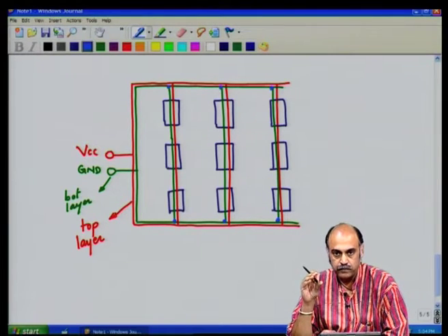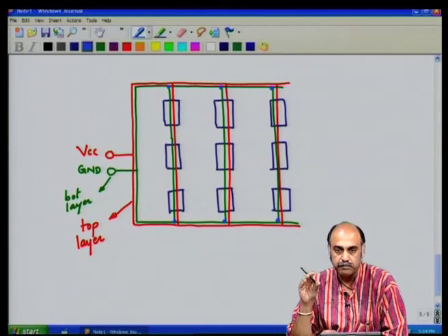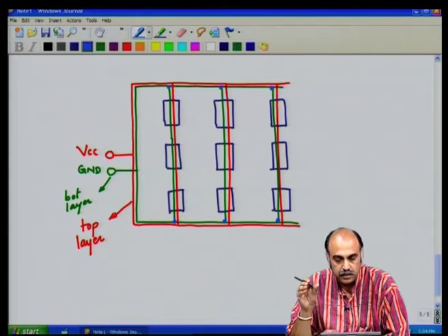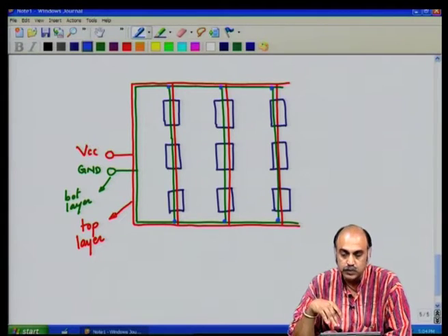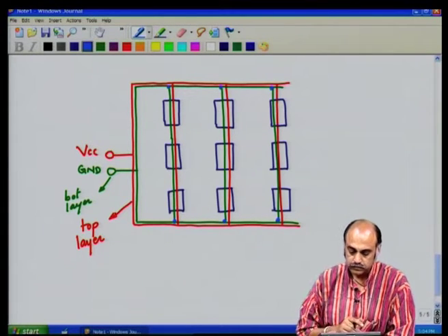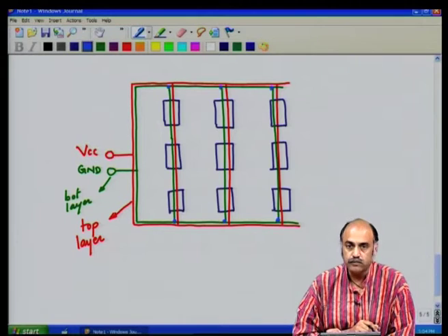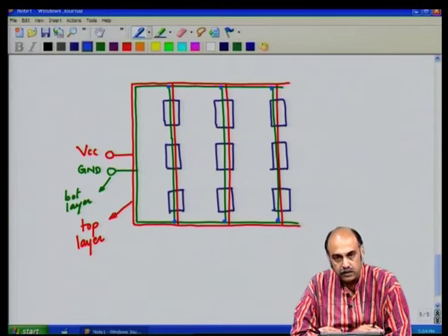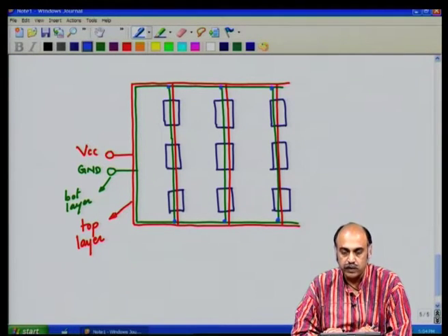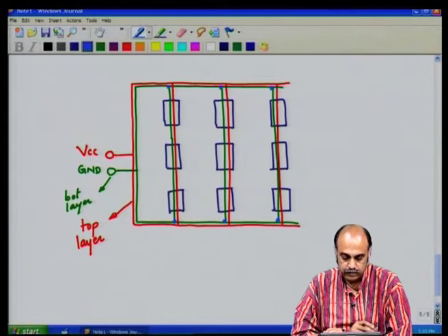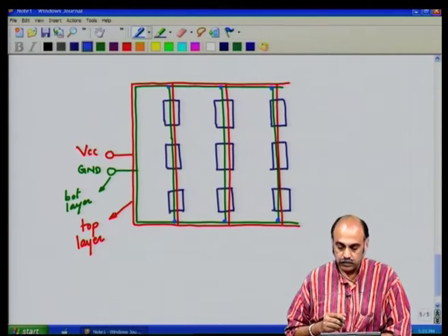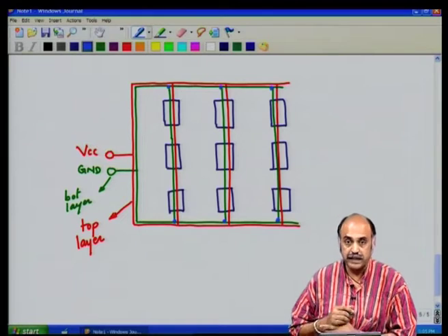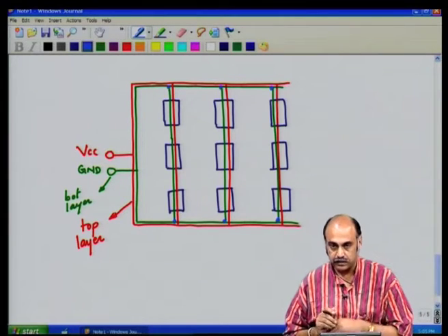capacitance, maintaining the capacitance for every centimeter run of the track length, and thereby having a good distributed capacitance. Of course, for the case of multi-layer boards, you are dedicating one full layer for ground and one full layer for the supply, and thereby you could have much better capacitances than before.